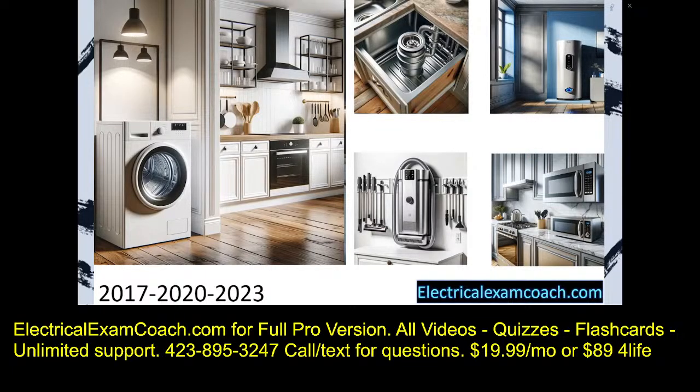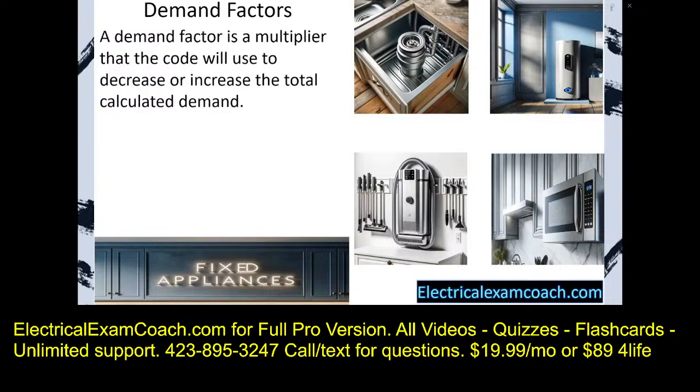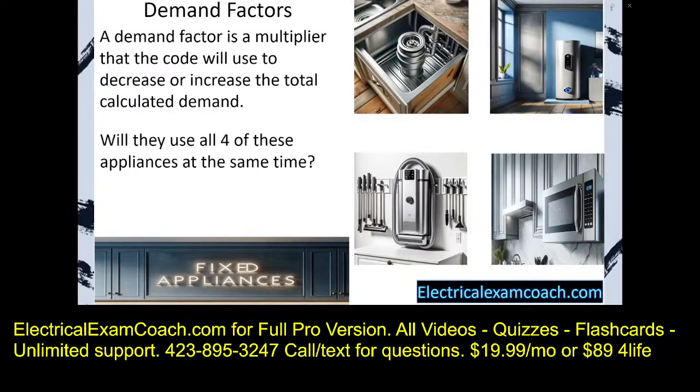Let's get to it. Before we dive into the calculations, let's learn about demand factors. We're going to be using them for the rest of the program. A demand factor is a multiplier that the code will use to decrease or increase the total calculated demand. The question is, will they use all 4 of these appliances at the same time? And the answer is no. So the code makers have made it so we can reduce the overall demand. Instead of just counting them watt for watt, they've made some multipliers that allows us to reduce the demand that we calculate. And remember, if we have less amps, we could have a smaller service. If we have smaller service, we could have smaller pipe, smaller wire, and a smaller overall cost of the job.